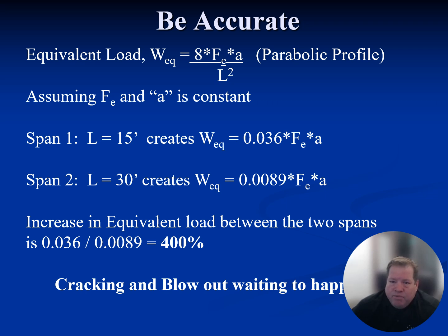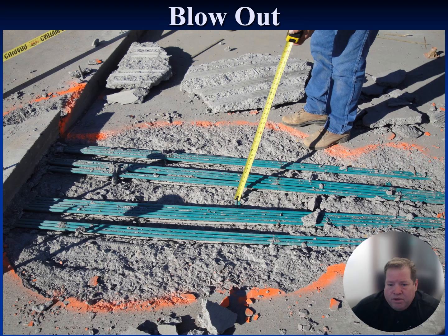Design PT, the least amount of PT possible, design it accurately. And if you're concerned, if you're nervous, you want to be conservative, which I do all the time, do it with rebar. Rebar doesn't create cracking. I've never seen rebar create a blowout, and it's great for crack control. And if it's never used, it's always there. There's no downside to it. You're accurate with PT, you're conservative with rebar.